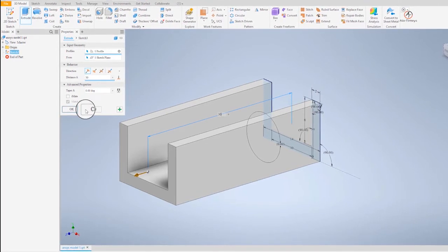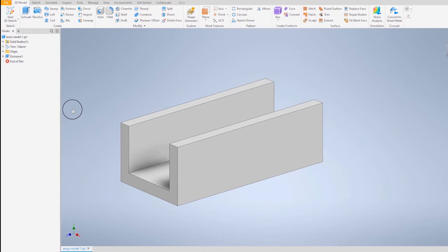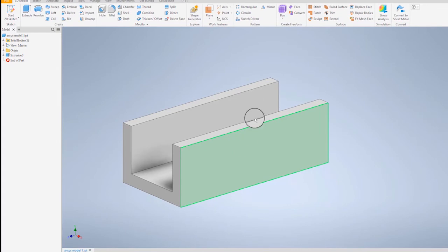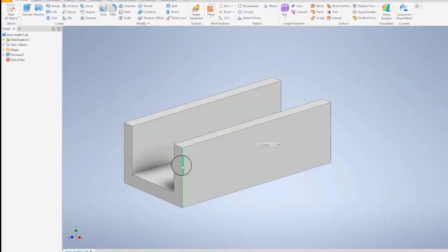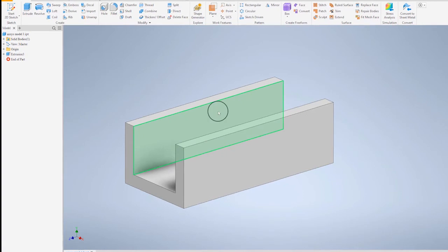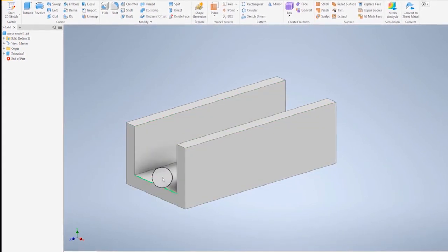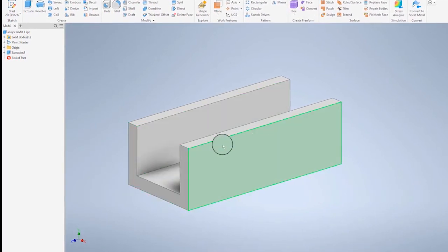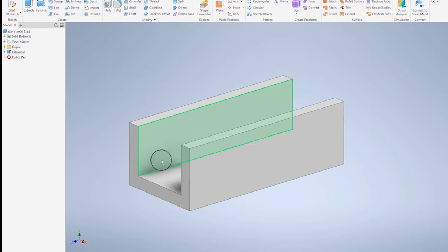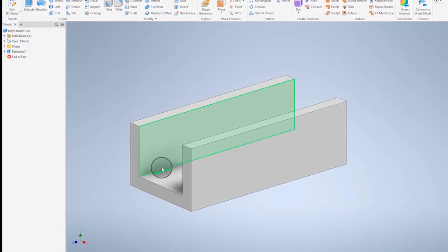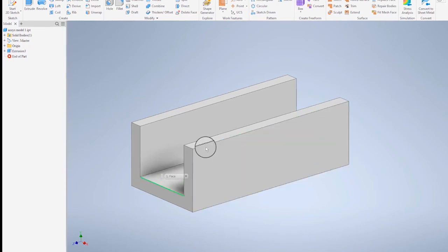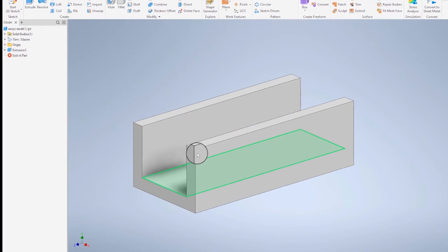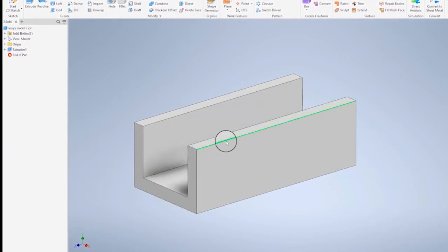Yeah, this is a very basic shape, but I'm intentionally doing it here so you can see what I am doing. From this point now, we need to also make a liquid body. And the truth with Ansys is that you don't have a void space in Ansys. We want to say water flows through this channel, or in the Nigerian setting, we say it's a wastage, drainage, or gutter, as the case may be. So we want water, or a liquid medium, to flow through. So we have to model that liquid medium. You can't tell Ansys that this is free space, just put something there. No, you have to put a solid body there.